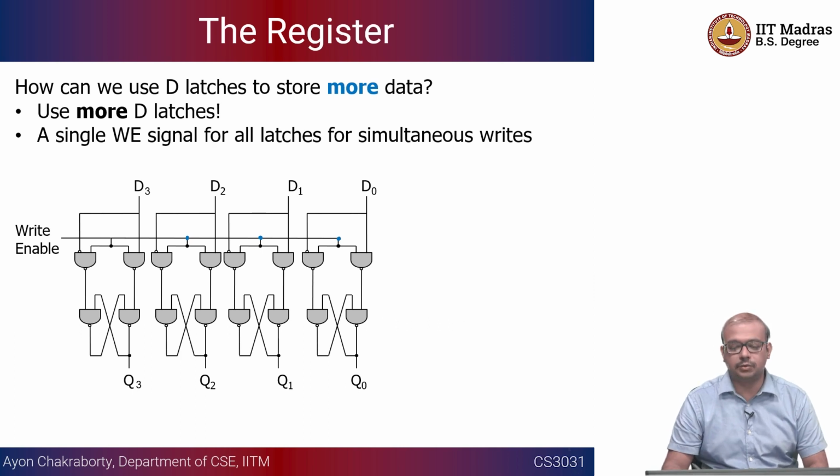The register is going to hold a binary number, and the size of the binary number is typically the size of the register. The size could be 8 bits, it could be 4 bits, right? Typically 8-bit registers are commonly available. So you will have these 8 bits to be stored, right? And you can read from the register, you can write to the register, and you can have this write enable on. If the write enable is on, you are trying to write to the register. If your write enable is off, you can read from the register. Okay, so note that you also have to provide the clock pulse, right?